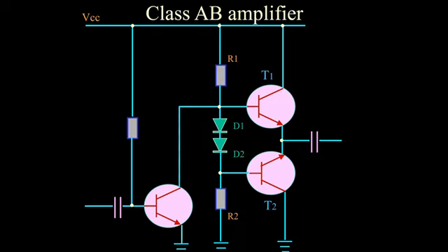They have also used two diodes so that these diodes overcome the crossover gap, I mean the changeover from conduction of one transistor to the other transistor. The diodes they have used fill that gap, so that they get a perfectly matched conduction. There is no time gap.